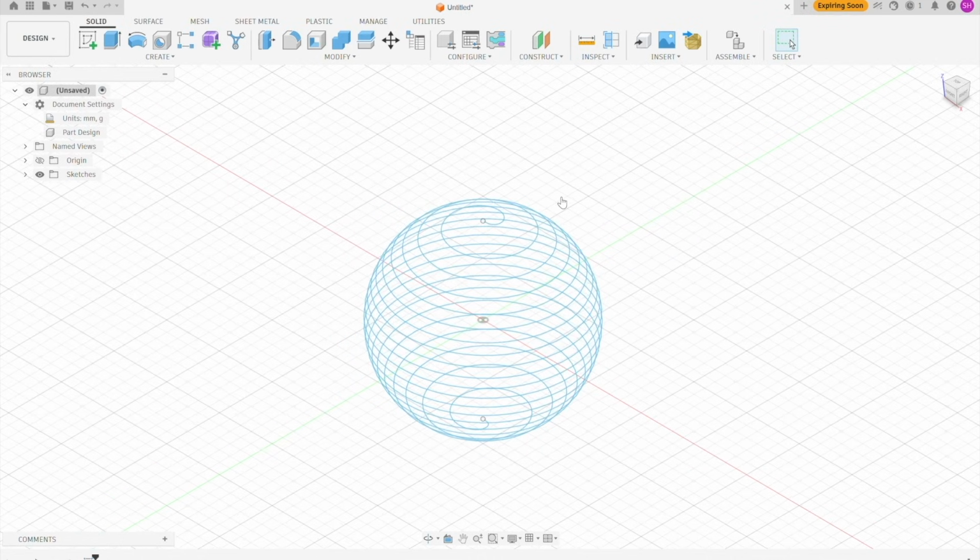So our strategy is to use the coil's CSV coordinates as a path, and we will draw a rectangular box which will simulate the multiple layers we will add based on the dimensions of the wire, more specifically the diameter of the wire. And then we will use that rectangle as a profile to sweep around this path. And then we will create a sphere, which is the holder, and then we will extract the path from the sphere and we'll be left with the holder.